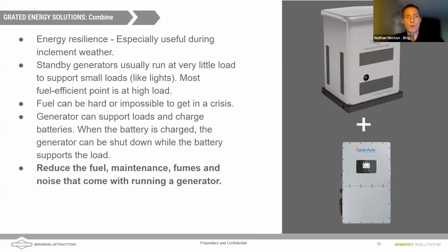And I think as installers, we know that dropping a screw down in there or just trying to get terminals threaded, that kind of thing, can be challenging. And so we make continuous improvements on that. And I did want to add one more thing about generator integration. I mean, there's no reason you couldn't put a 26K on the 80 amp port on the Solarc. You could just limit how much power you're going to pull from that port, right? And so you just wouldn't be able to pull all 26K. You'd be able to pull 19K through the generator port on the Solarc.